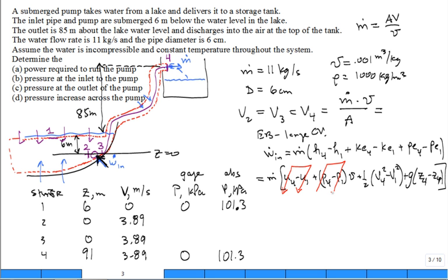They're the same pressure. We just talked about that, right? Okay. What is V1? So what I'm left with is the statement that says the power that I have to supply the pump is proportional to the mass flow rate through the pump. If I'm putting a lot of fluid through the pump, I'm going to need a bigger power source, a bigger motor to drive it. Okay?